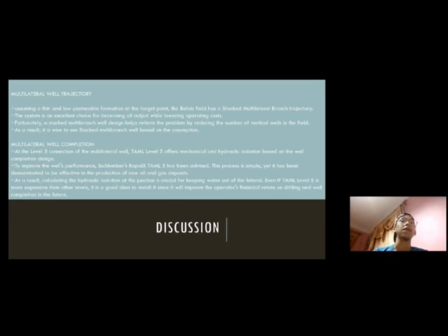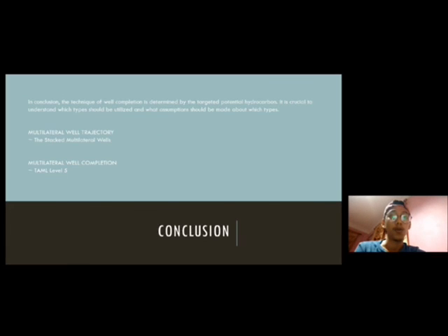And for the conclusion, the technique of well completion is determined by the targeted potential hydrocarbon, and it's crucial to understand which type should be utilized and what assumptions should be made about which type. And for the multilateral well trajectory, we choose the stacked multilateral wells, and for the multilateral well completion, we choose TML level 5 for the design.